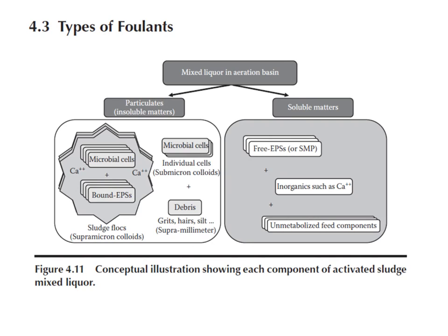Particles include microbial cells, cell debris, and sometimes other debris like grit, hairs, and silt in the MBR system. Microbial flocs are the main components of the particles in the mixed liquor, and they include the microbial cells as well as bound EPS.